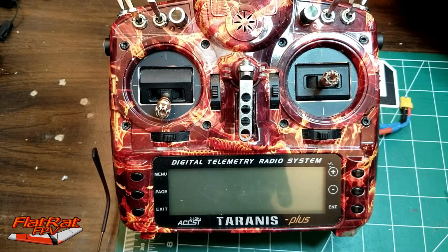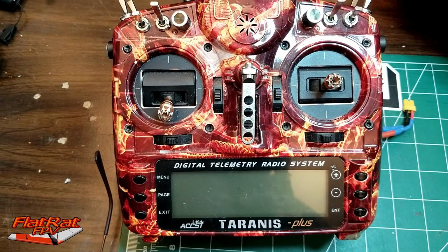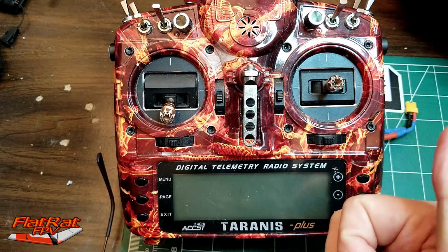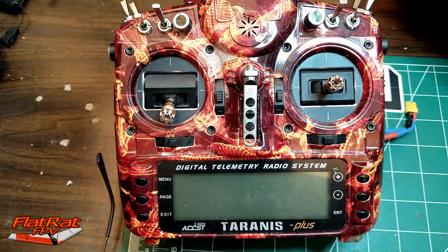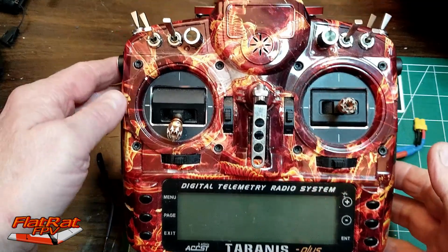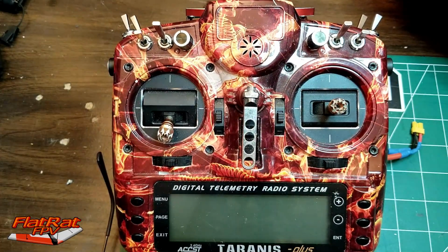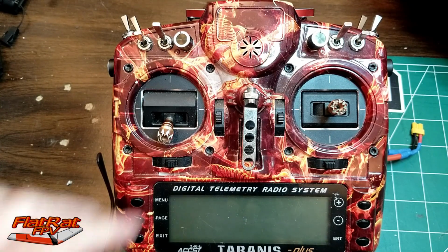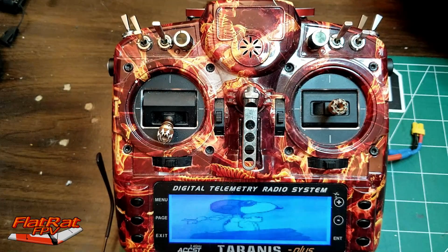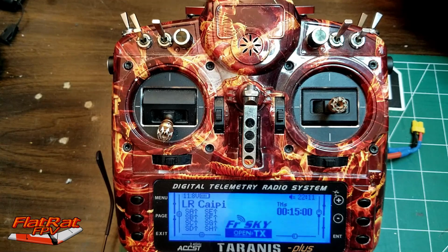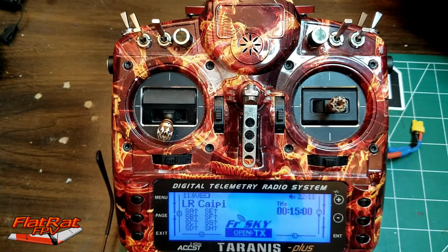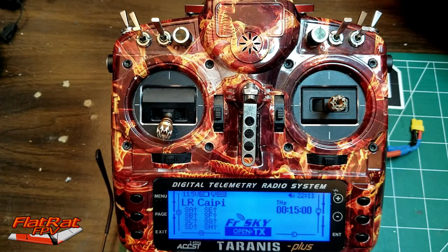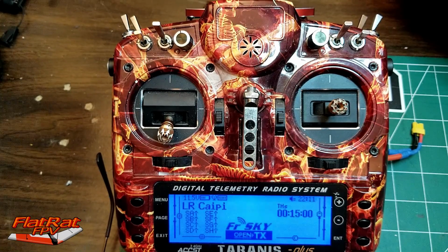So the big thing is that you can't do this from the DJI menu. It has to be done from inside the Vector unit. Now, the particular Cappy right here is using a micro Vector. I've got several others that use the large Vector, and the process is the same because the OSD menu is going to be the same in each one, okay? So we're going to power up the radio. We're going to power up our model. Again, it doesn't really matter which model it is. The process is going to be the same for either one of them, okay?